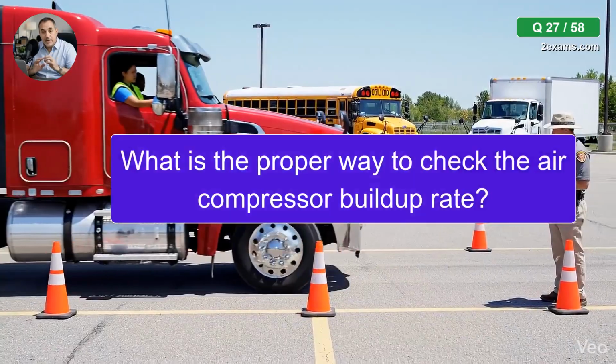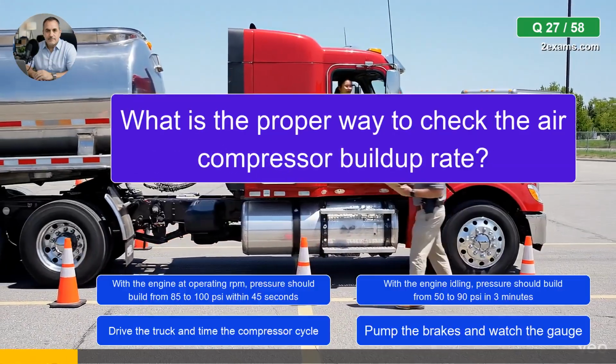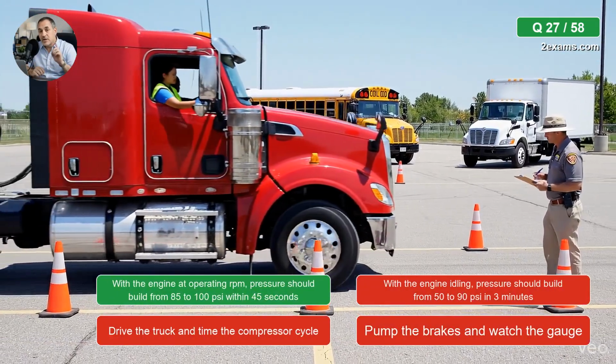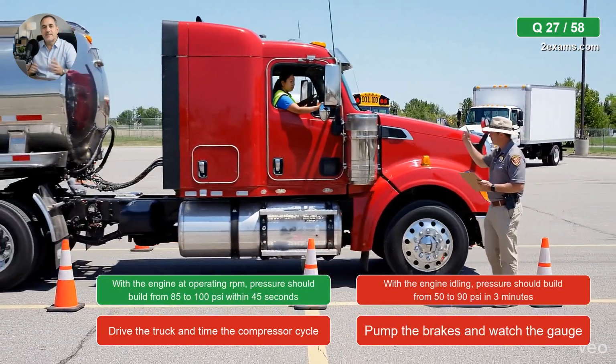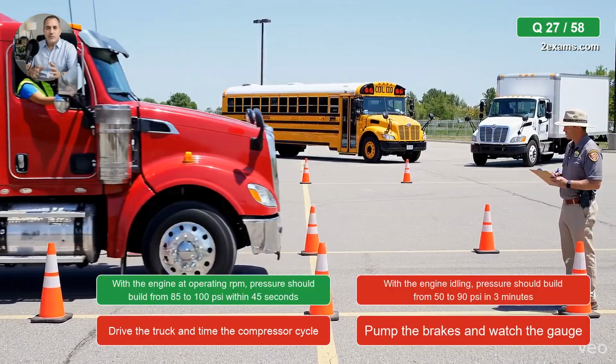What is the proper way to check the air compressor buildup rate? The correct answer is, with the engine at operating RPM, pressure should build from 85 to 100 psi within 45 seconds.